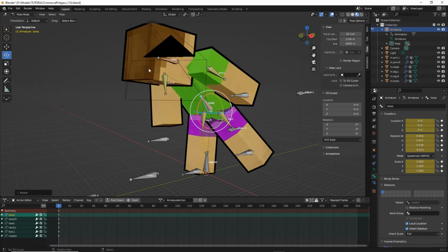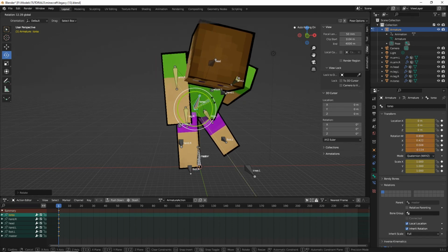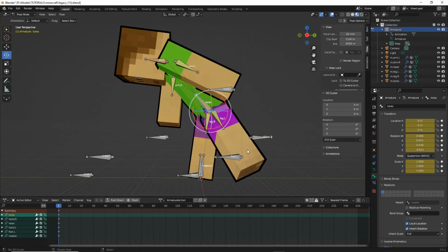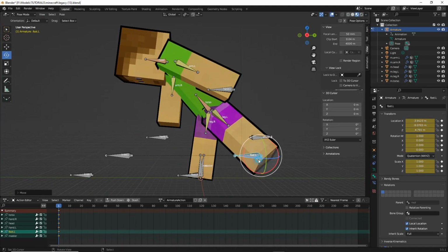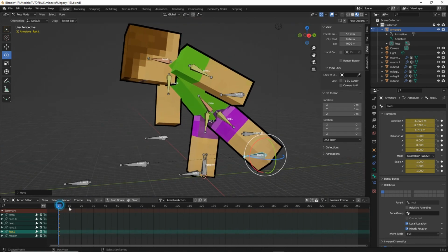And we can see that as we move, well, this torso bone in particular, as we move that bone, the IKs that we set up soft lock the limbs in place. They're essentially tracking a position rather than being fixed to it. So let's call that our pose.